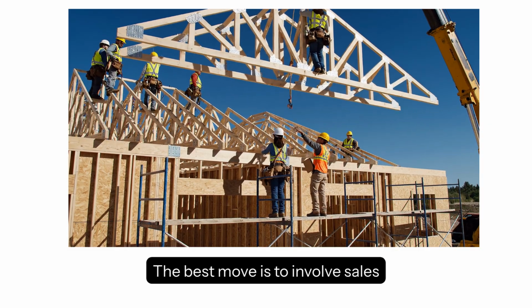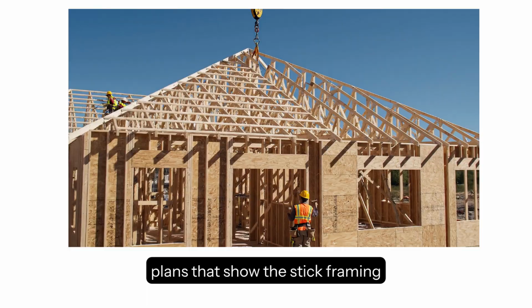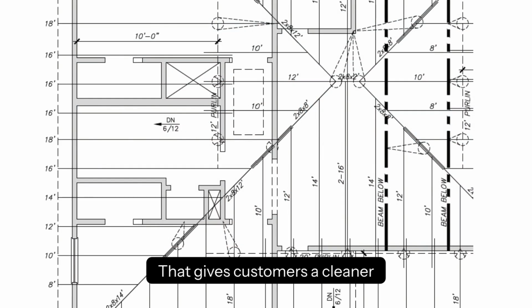The best move is to involve sales early and ask for a detailed set of plans that show the stick framing and loads being transferred to the floor system, or push to convert stick frame roofs to truss systems. When the roof system is engineered, the load path is known, and walls, headers, floors, and bracing can be designed correctly. That gives customers a cleaner structure, gives suppliers clearer responsibility, and gives the whole project a better chance of staying on time and on budget.